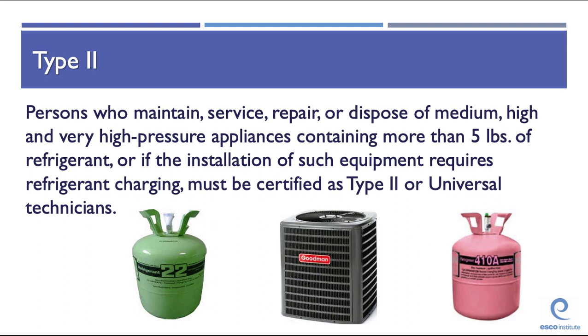High pressure refrigerants have a pressure between 155 psi and 340 psi at liquid phase temperature of 104 degrees. Medium pressure go between 30 and 155 psi at liquid phase temperature of 104 degrees. Type 2 certification does not include small appliances or motor vehicle air conditioning systems. Most technicians will need to be Type 2 certified or have a universal.